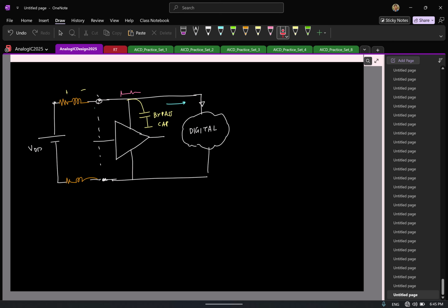But the problem is the following: the output voltage, we are defining it as the potential difference between this local output line and the global ground line. Now this line is local to the block, so it is okay. Whereas this line is common to all the blocks, so you have a lot of disturbances here. Correct? So if you want to eliminate any effect of the global lines on my output, what do you think I can do?